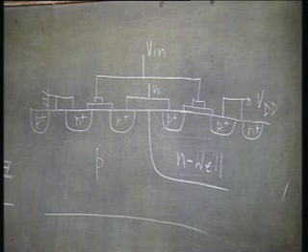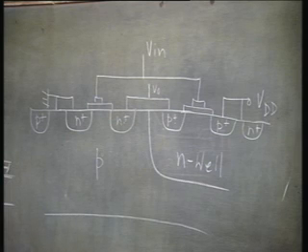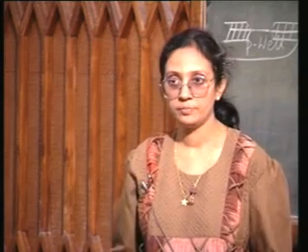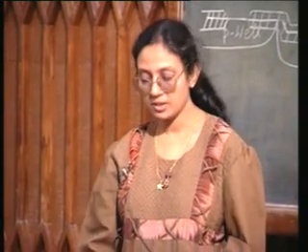One way you can prevent this latch-up is, you see, essentially we have two transistors, NPN and PNP, by keeping the beta of these transistors low. Okay. This is the older technique of keeping the beta of the transistor low, that was by doing gold doping or neutron irradiation, so that the lifetime is killed. But these techniques are not really used very much these days, because you can't accurately control them. So, that technique of controlling beta is not very much in use.